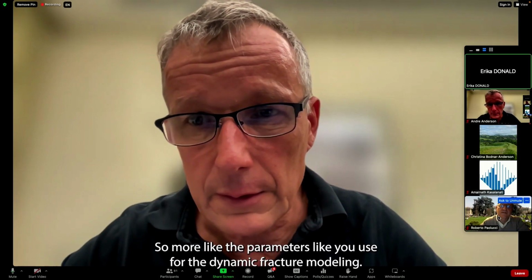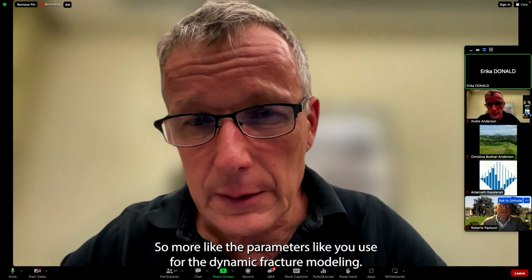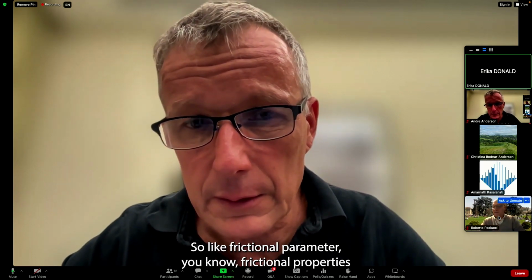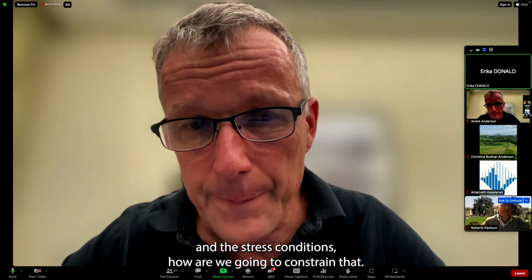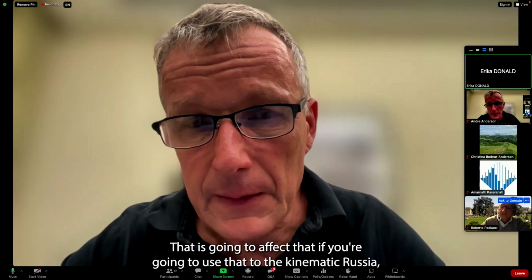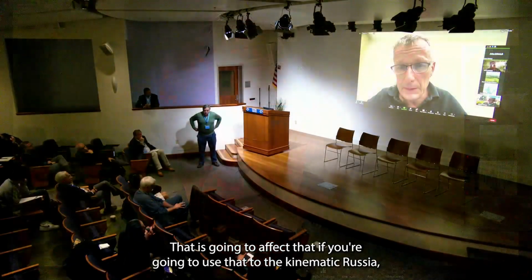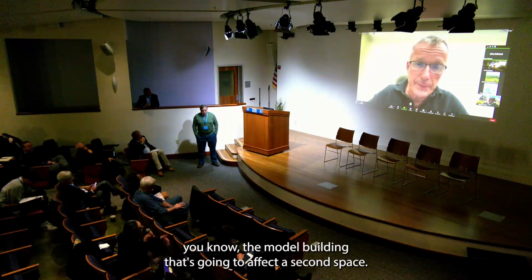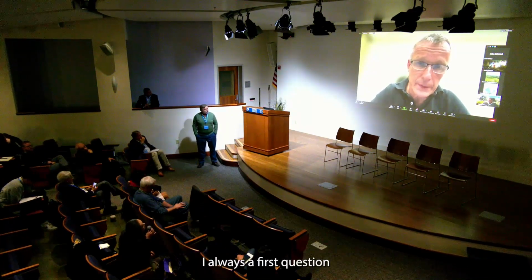The first question is about the parameters you use for dynamic rupture modeling, like frictional properties and the stress conditions. How are we going to constrain those? Because if you use them for the kinematic rupture model building, that's going to affect the second step. That was the first question.